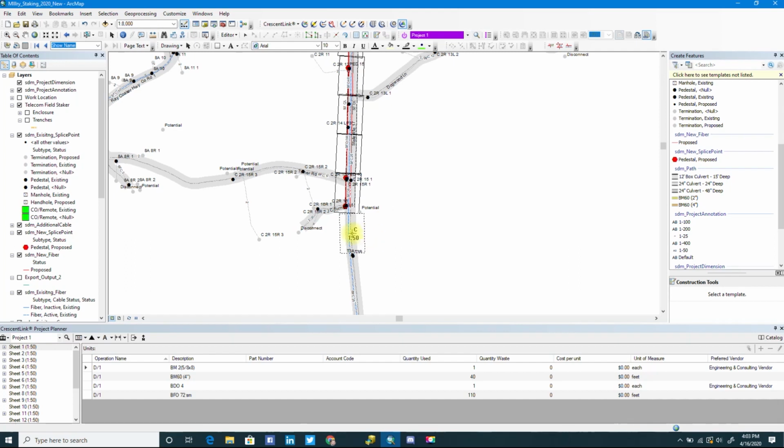And I can just come in here. Once I get it lined up where I want, I left click to set the sheet. And then you notice the sheet stays in the last reference that you used. So if you're going down a road, you could just click, click, click, click, adding sheets down through there. When you get ready to change the orientation again, simply right click, get the dog ears, and you can adjust the orientation that way.